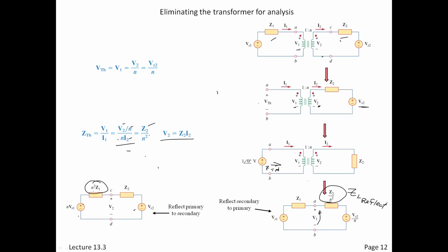So primary impedances reflected to the secondary, well, I was going to say increase, but N might be a fraction, right, if it's a step up or a step down. So this will be taken care of in that fact. Just like here, if N is a fraction, Z2 will actually come across as an increase. A fraction would be if it's a step down.